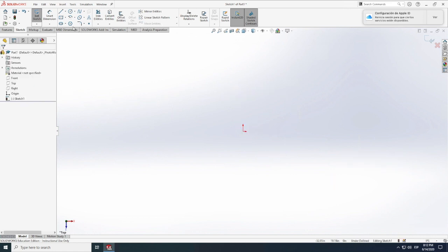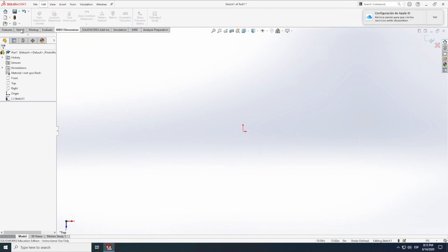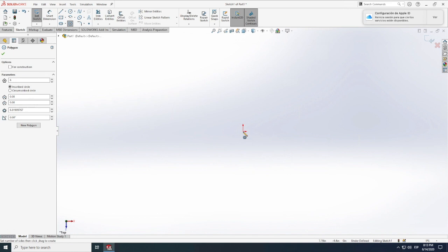And then, some other different figures that you can do is this one, for instance, which is a polygon. So let's go ahead and... it disappeared. Messing around. So let's click in there. And then let's go ahead and choose that point. So by default, if I'm not mistaken, SolidWorks will draw you a hexagon, as you can see over here. I just want this line to be level, parallel to the horizontal. It's just not working. Don't worry, we'll just leave it like that because we can define a couple of variables here. So there, it says 6 sides. Let's go ahead and go for 10.